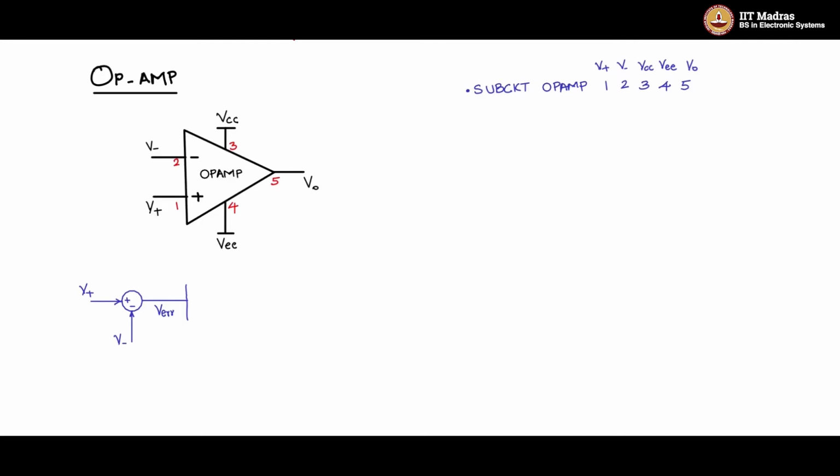A close approximation would also be a PI controller, where a PI controller has a gain of almost infinity towards DC because of the I part, and then the gain starts tapering off. It is also something like a low pass filter. So the proposal is that I will use a PI controller type of a filter here for acting as the gain. So this will give infinite gain at lower frequency and DC.